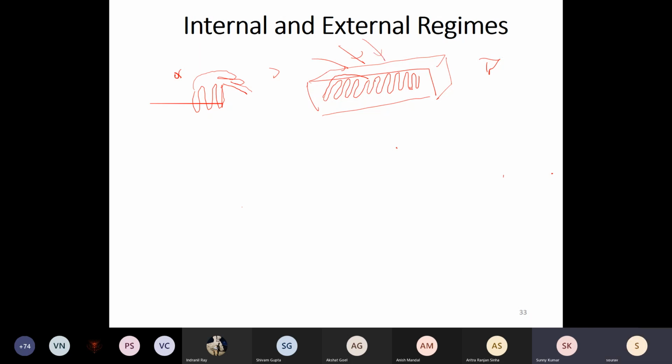And air enters from the top, blows across this triangular arrangement, and then is blown from the bottom into the room. And the fan itself is placed over here. So it sucks in air from the top. And hence the indoor unit should be placed typically around 6 inches below the ceiling.